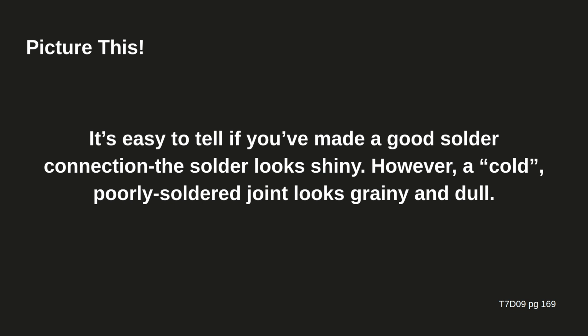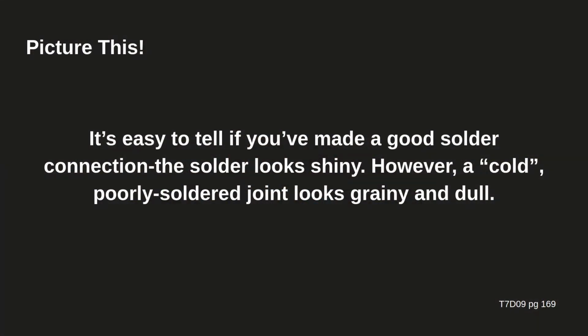Now, has anyone in the chat room done any soldering before? If you have, then you know how this works. If not, then we'll teach you a little bit. It's easy to tell if you made a good solder connection if the solder looks shiny. It needs to be a shiny look. However, a cold, poorly soldered joint will look grainy and dull and won't hold as well.